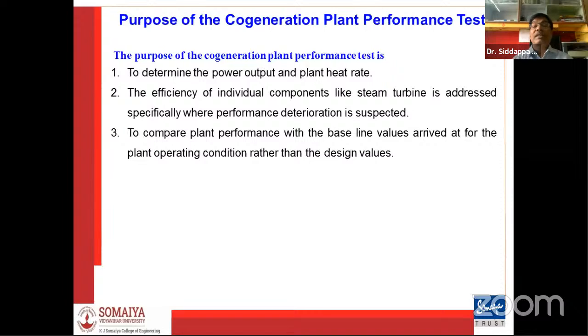For example, we can say the engine will give more power at 5000 RPM. The engine gives more power at some 75% of the load. These are called the baseline values. Now it is always mandatory for us to test the equipment at baseline values, whether it is giving the rated amount or the specified amount or not. Design values are different. If I say a 40 HP engine, the 40 HP you are going to get when you run it at full load and full speed, or at its extreme conditions for what it is designed. That is called the design value.